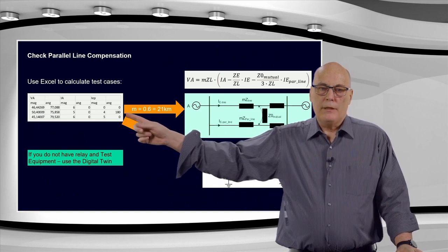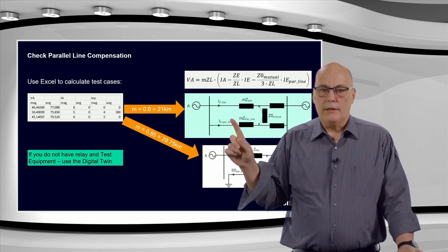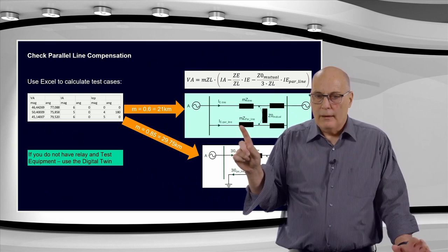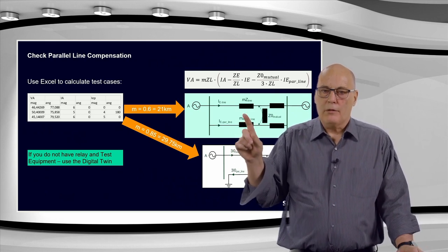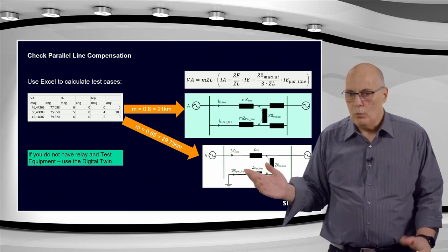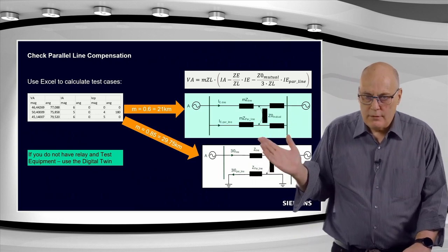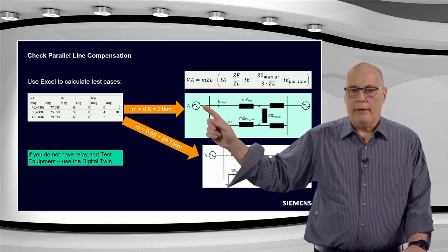So the 4 amps here, that means we have in this second test case 5 amps here and 4 amps over here, and the ground currents are parallel. Normal application, remote fault, and again it was at 0.6, just to compare the two results.